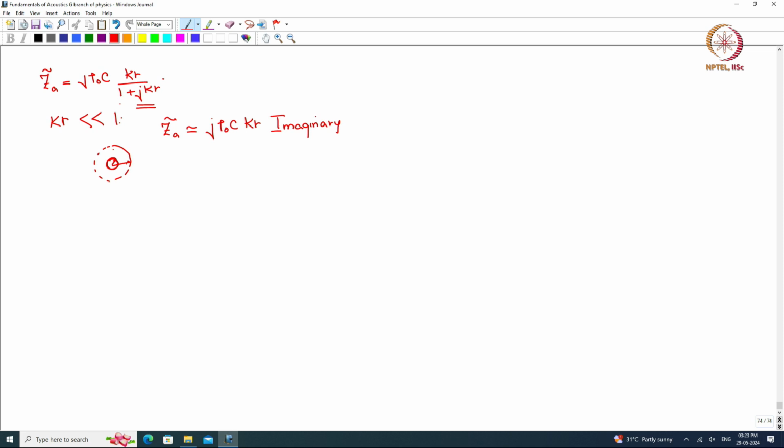If the impedance is imaginary, we should know that typically these are supposed to have a real part and an imaginary part. The real part indicates dissipation and power transmission, whereas this is indicative of non-dissipative aspects such as stiffness and inertia.